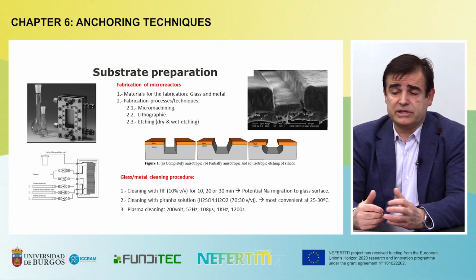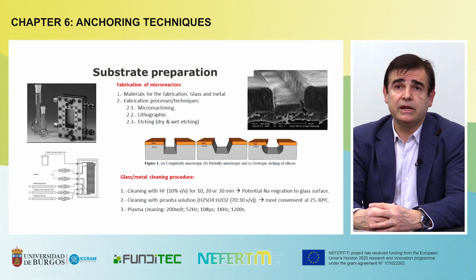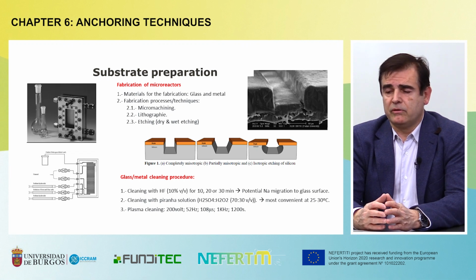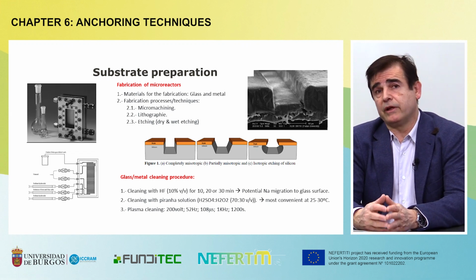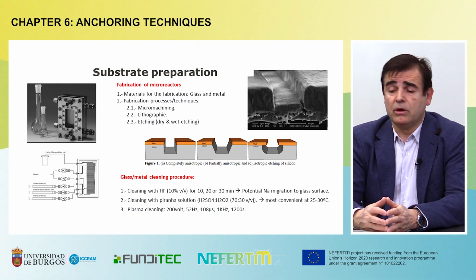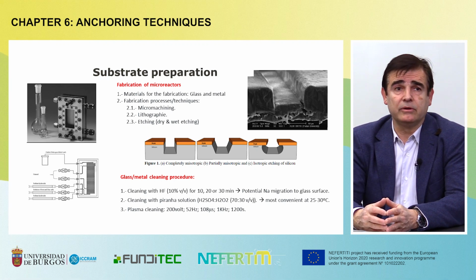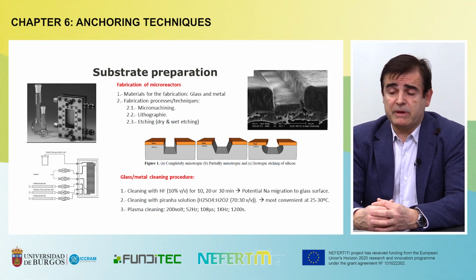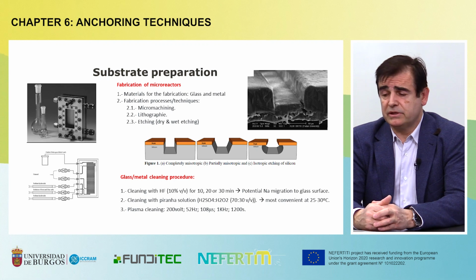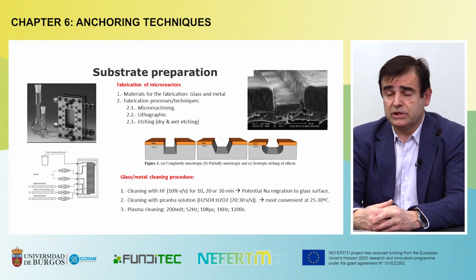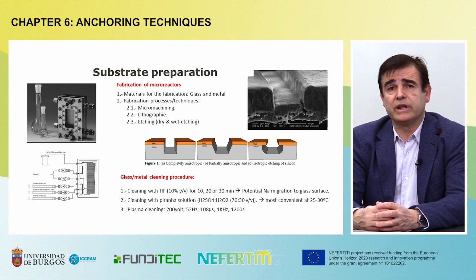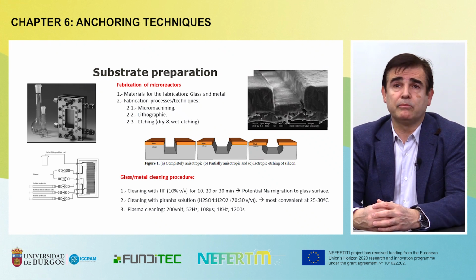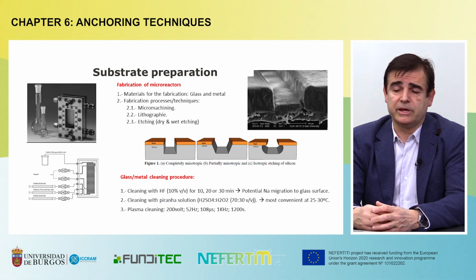Prior to catalyst deposition, the channels must be cleaned and activated. Two main methods can be used: chemical cleaning with hydrofluoric acid or piranha solution, or physicochemical cleaning, for instance, the use of plasma activation. All of these methods produce an activated surface containing hydroxyl groups that later on will be used to anchor the catalyst. The process can be done directly or through intermediate molecules called anchoring elements.